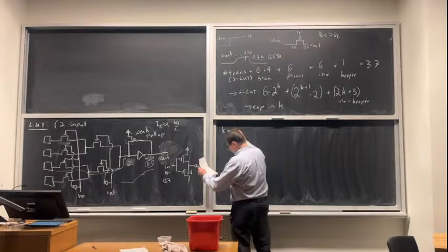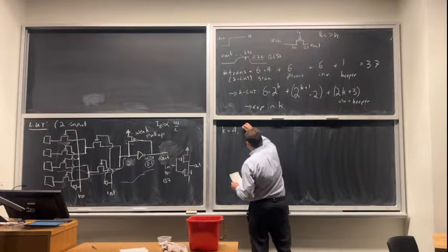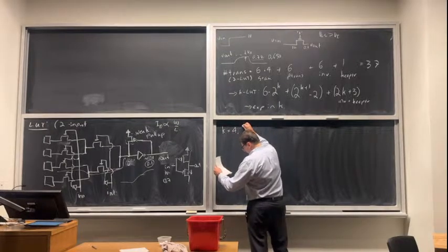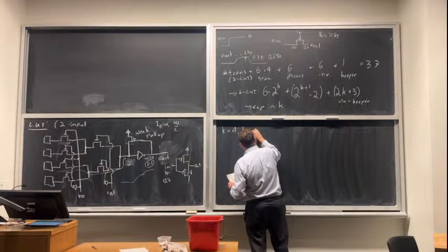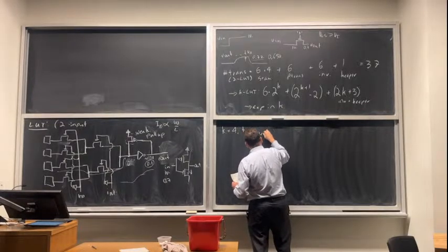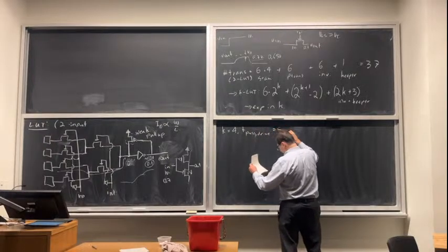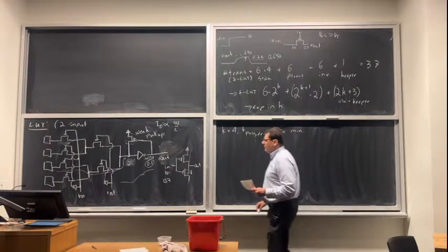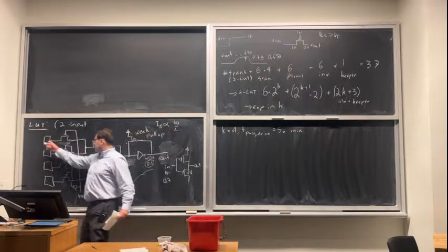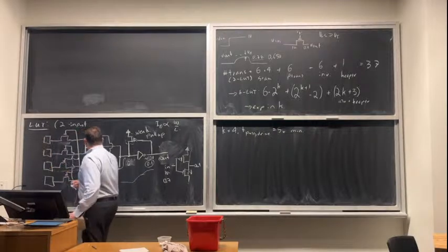So let's say we're going to do a 4 input lookup table, and we want the pass transistors to have 5 times the minimum drive strength. So 5 times the minimum. All right, so the SRAM cells, you can use really small transistors. They're just holding state. There's no speed requirement on them.